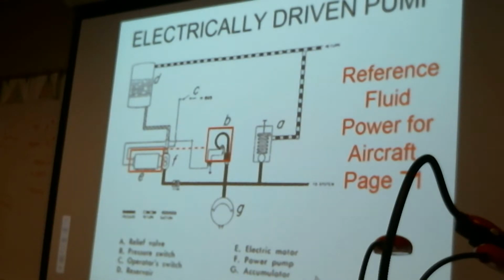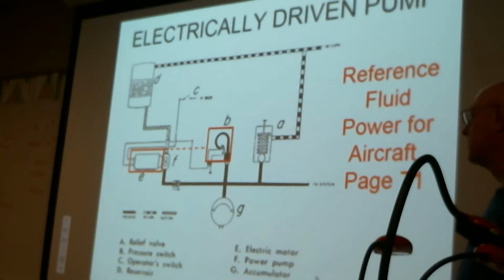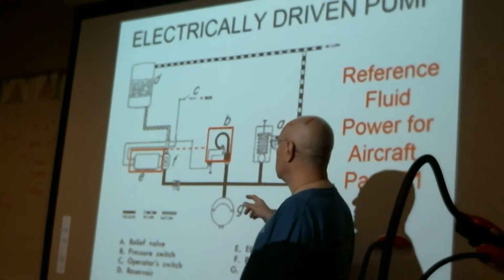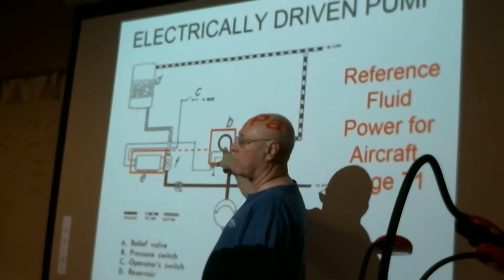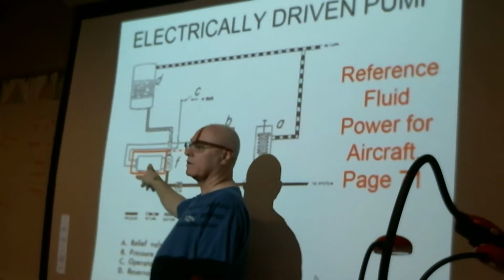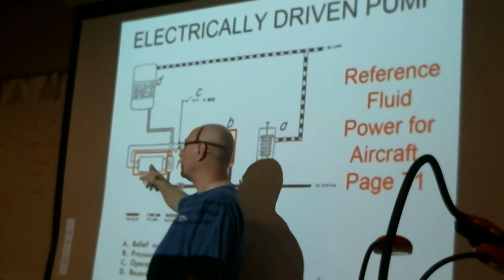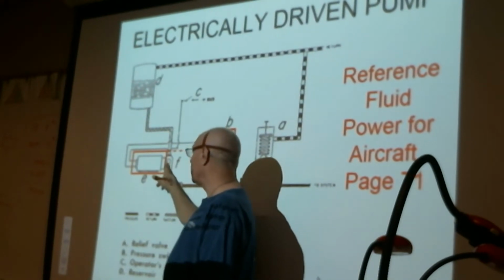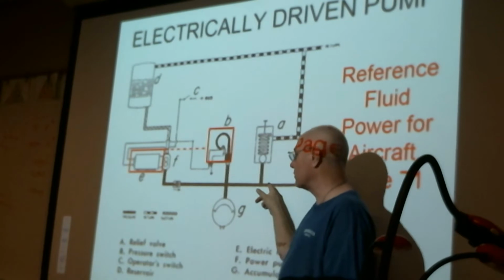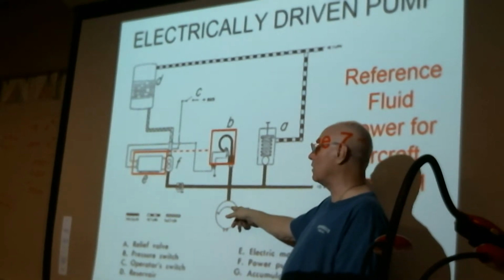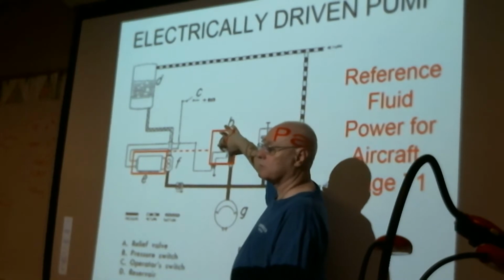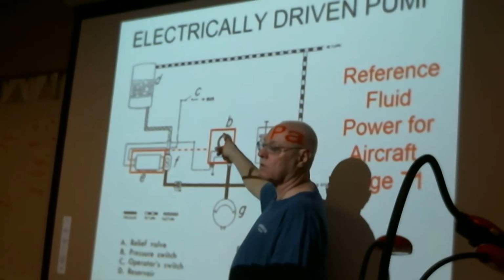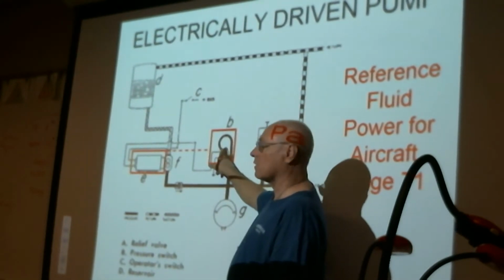And the pressure switch, in this case, is what we call a normally closed pressure switch. You can kind of see what happens. When we develop current flow through the electrical circuit and the switch contacts are closed, that's what's energizing the electric motor, and then the pump begins to turn. When the pressure builds up in the pressure manifold and starts to fill the accumulator, at some point the contacts on the pressure switch will open because the Bourdon tube starts to go erect, and then the contacts open.